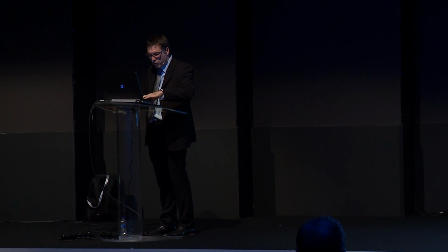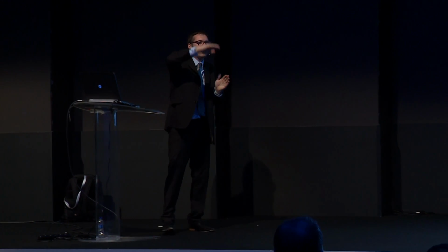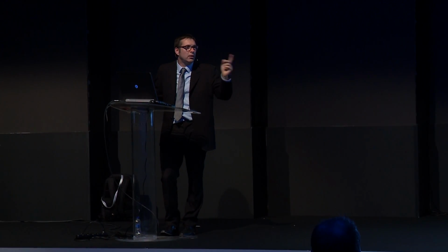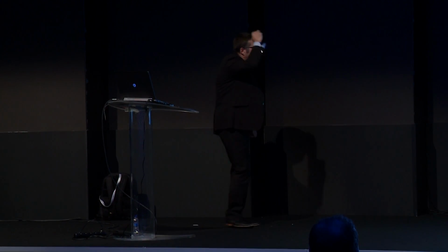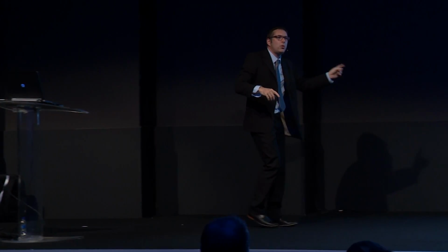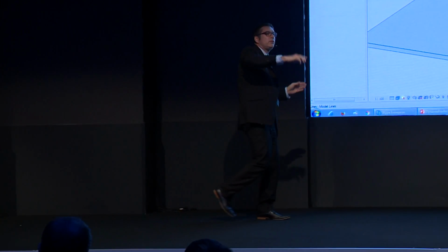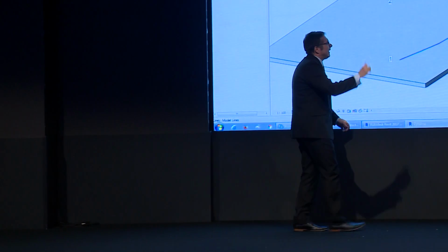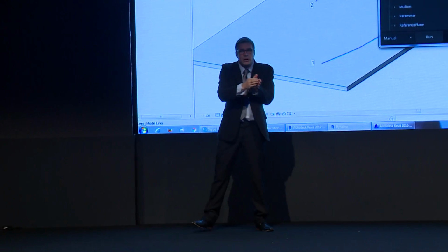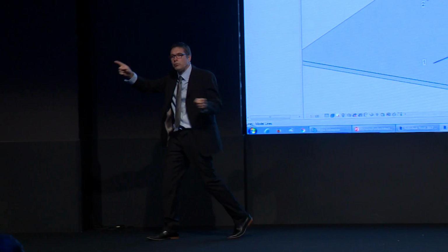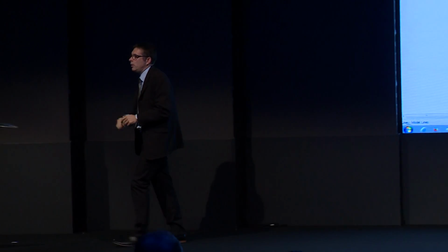The next step will be to create some nodes along the line. I've created here a code block as I used before. It is a list of numbers, 0 to 1. 0 is the beginning of the line, 1 is the end of the line, and I use x as a variable. It's the number of nodes between the start and the end of the line.